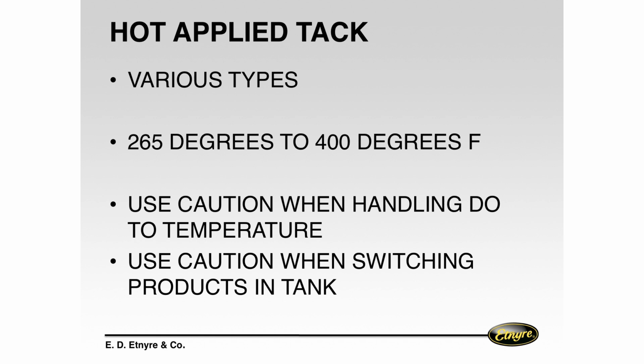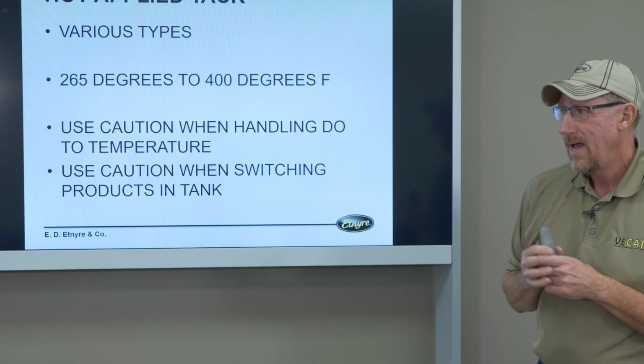So hot applied is a whole different story. Now instead of being 150 to 180 degrees, we're now 265, maybe all the way up to 400 degrees. Now that creates a lot of different problems. One is if you get it on you, you're going to get burnt. So you've got to be much more careful when you're using the products to stay safe with that, okay? Use caution when you're handling the temperature, but also use caution when you're switching products back and forth.